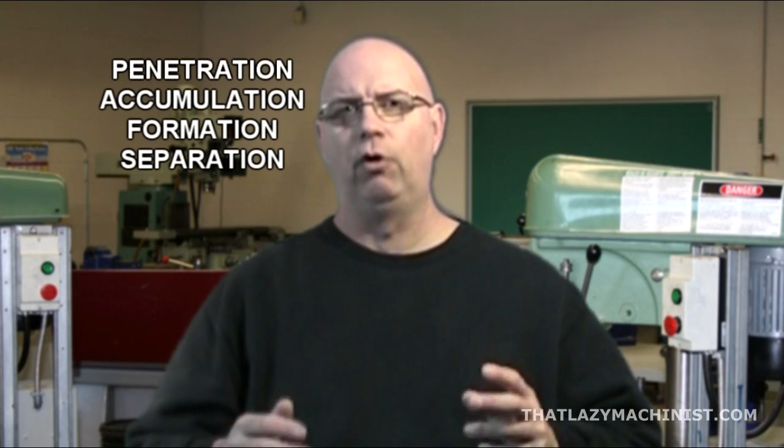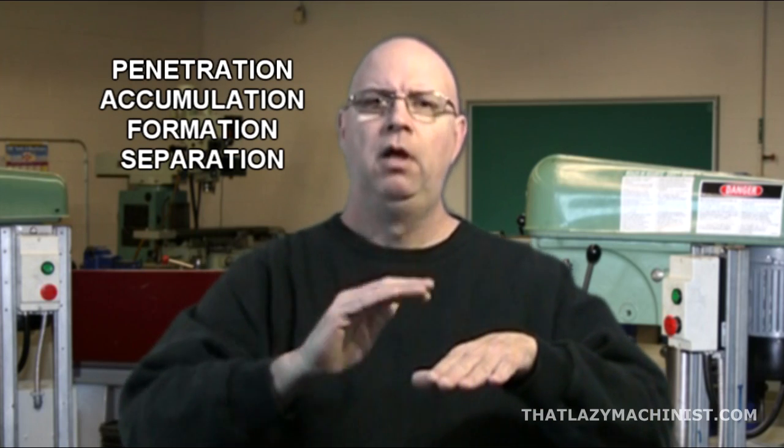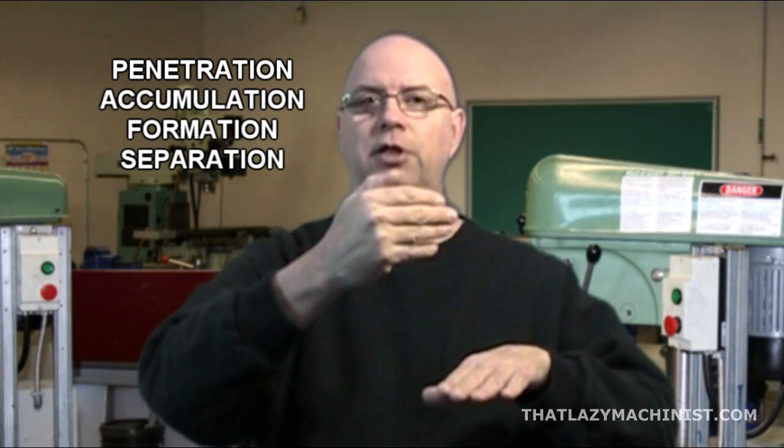We're going to be looking at three types of chips: continuous, discontinuous, and built-up or adherent chips. We're also going to look at cutting speeds, RPM, and feeds. So let's start by looking at the four phases of chip formation and the basic variables that affect that chip formation. Chip formation can be broken down into four steps: penetration, accumulation, formation, and separation. Let's look at each one of those steps in more detail.